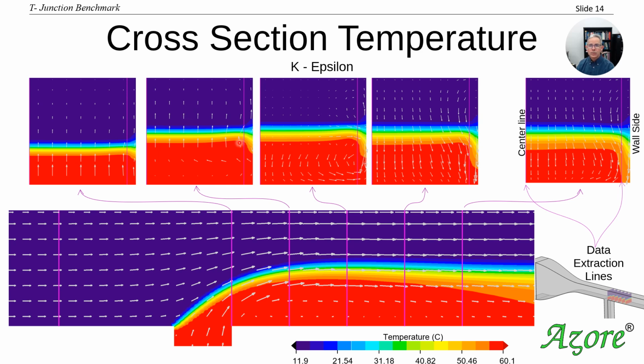But you also see that the flow structures are starting to change because of this recirculation zone. We're getting a little bit of secondary flow, meaning that the flow is actually going side to side in the ductwork right here. That's forming. Now, if we go a little bit further down, we're in the middle of this recirculation zone, and we can see that this secondary flow structure has developed pretty significantly. So we have some rotational flow right here and a secondary rotational flow here.